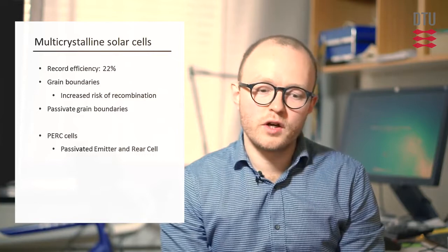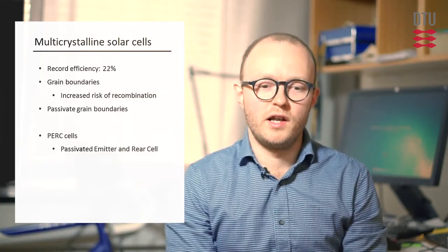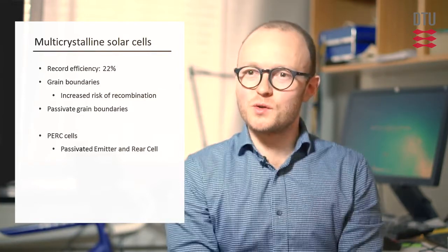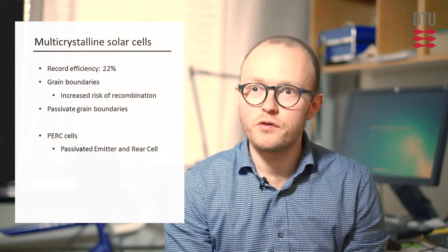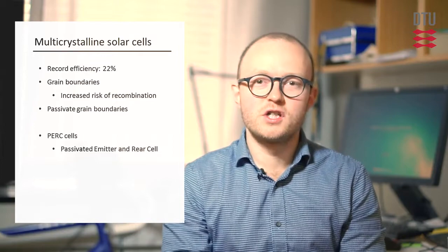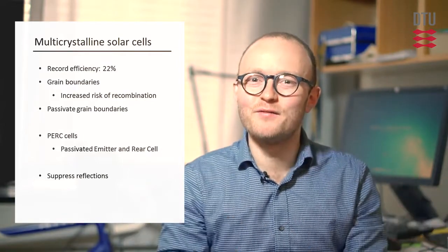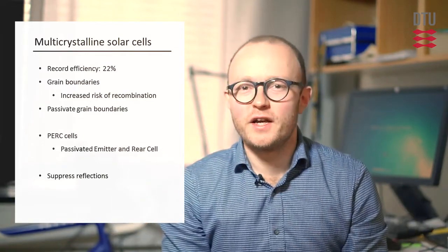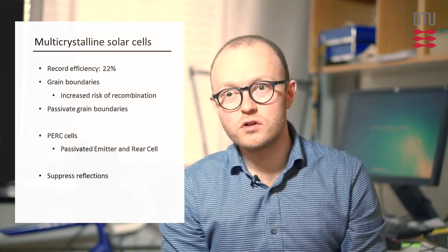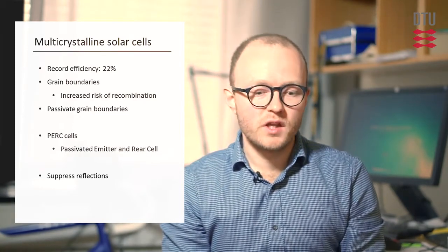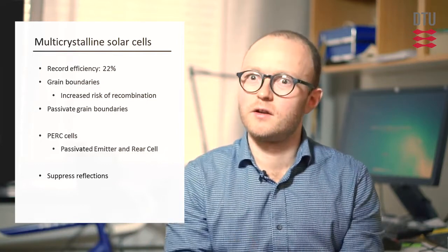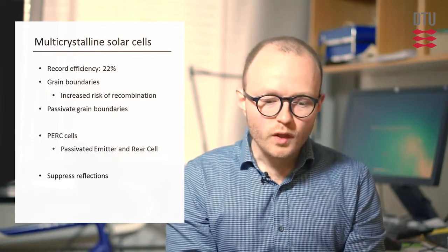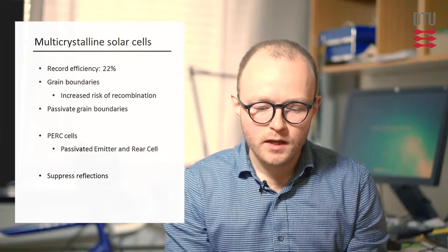If we then look at an electrically optimized multicrystalline cell and say, what can we do to push that further? If it's still blue when you look at it on the roof, it reflects blue light that could be used in the cell, especially if the front surface is well passivated, so short wavelengths can be useful when you look at the quantum efficiency.